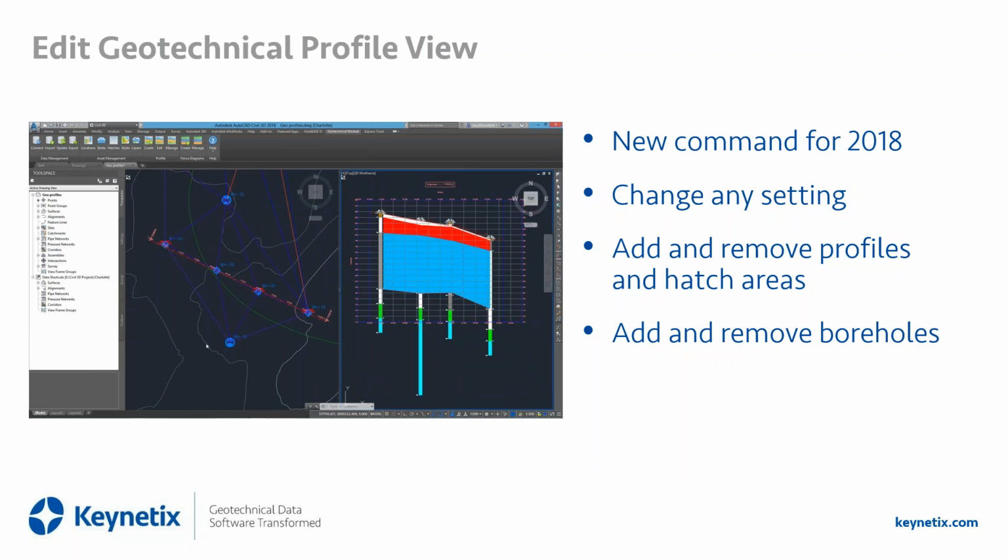Now what goes with the profile view is the ability to edit those geotechnical profile views. In the past, once you've created one, you could not change the log strip style. You could not add or remove boreholes to an existing geotechnical profile view. So we've added some of that functionality plus more into this new edit geotechnical profile view command.